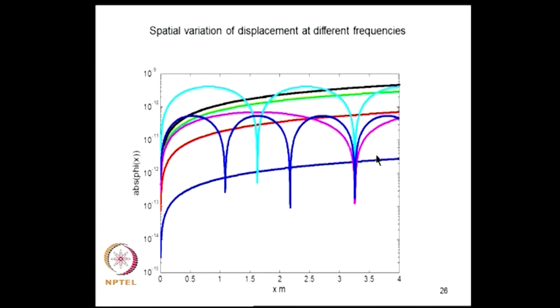So, if you are using a one mode approximation, you will be getting a straight line as a solution in a classical FEM. Okay. So, that is not acceptable if you cross the frequency and go to higher frequencies where we can expect to get more oscillations in space.